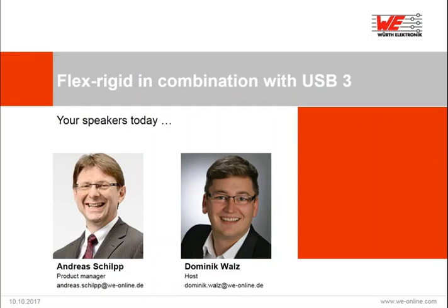So roundabout maximum 70% copper coverage. So it's not recommended to use less copper coverage than 70%. And we already had a lot of projects with different customers, and the hatching worked well.